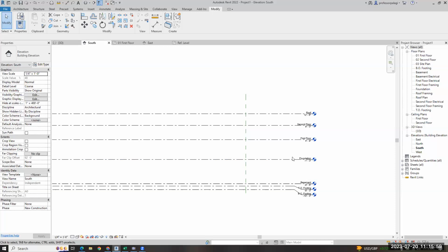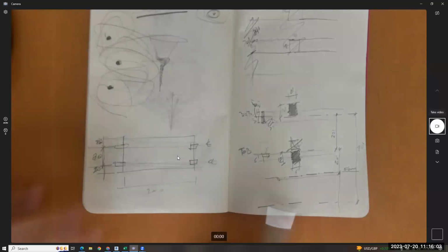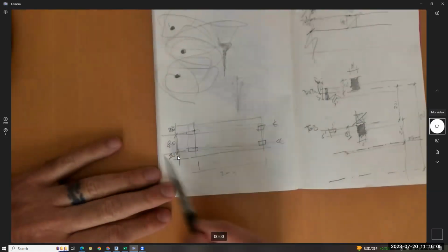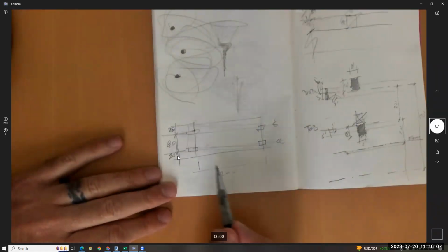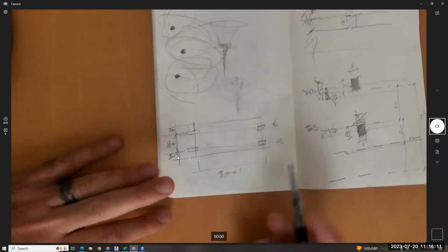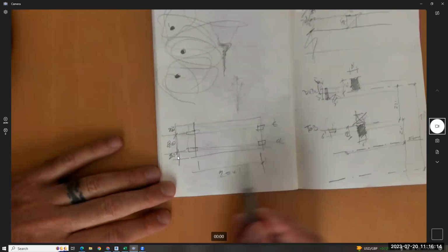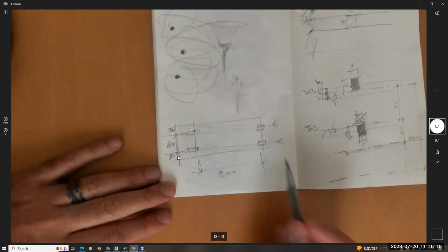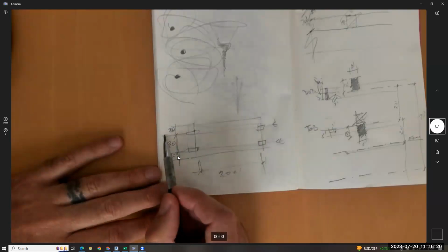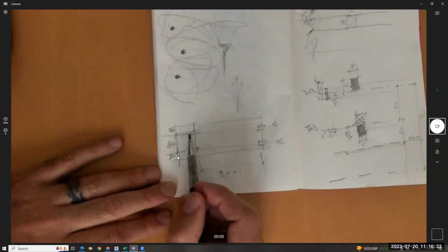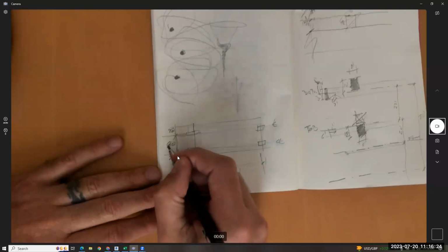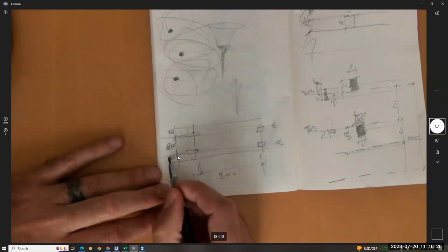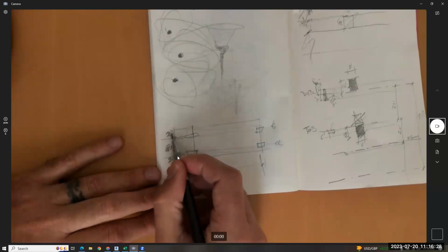Computers. Okay, so let's jump over to this first and walk through some of this. These are my scribblings as I was working through stuff; I made some rough estimates. I'm saying a 200-foot span. It's a little over that, I think, but I was finding some bad drawings that weren't really that close. So clear, I'm saying from the inside of that column to the inside of that column. I'm going to do the center line of this structure at 80 feet apart, and then 20 feet out, 20 feet out. Did anybody have any official numbers?